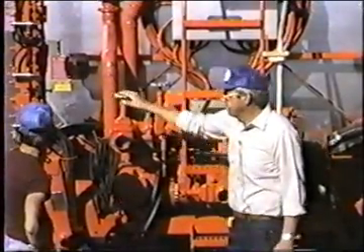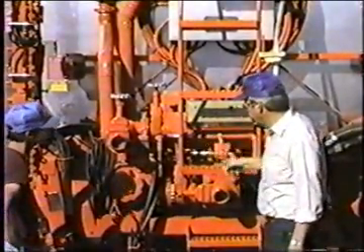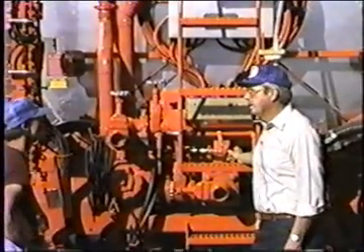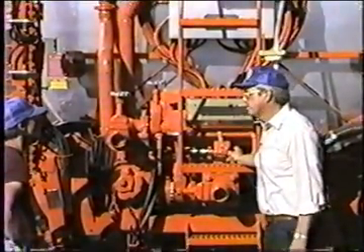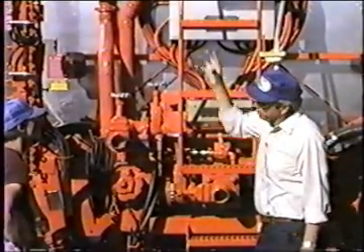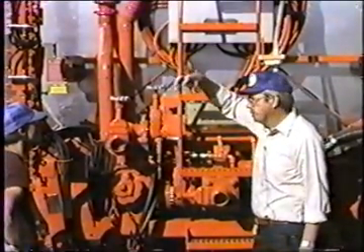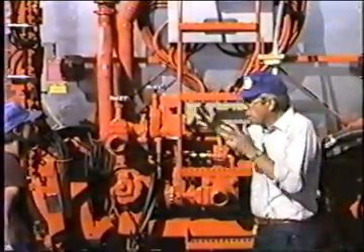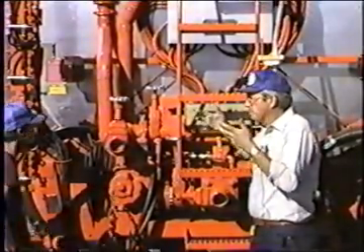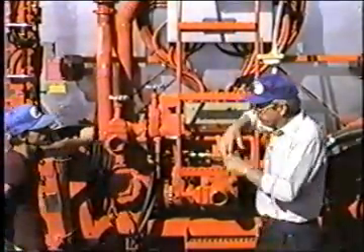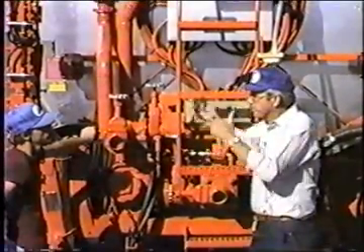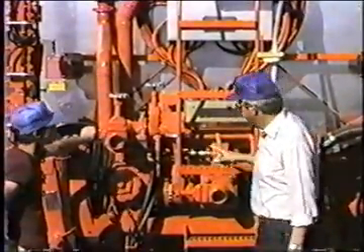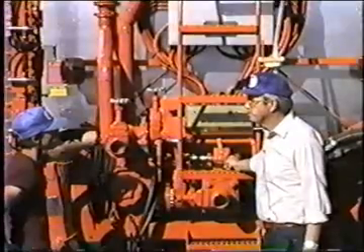Okay, the next advantage is that we are pushing the material in the bottom of the tank. There are a lot of asphalt materials, specifically emulsified asphalt materials. If we push them over the top of something or dump them in the top of a tank, they foam up real bad. And I mean, they really foam up. If we push in the top here, it foams up and the tank will run over when it's half full, with all this foam coming up out of it. If we push it in the bottom, there's no foam.